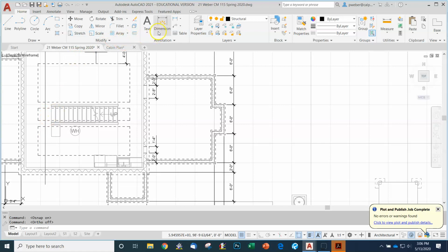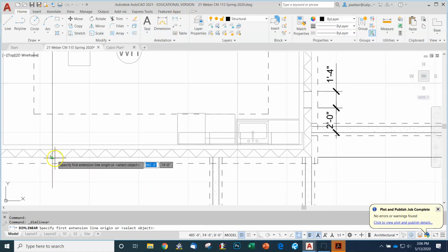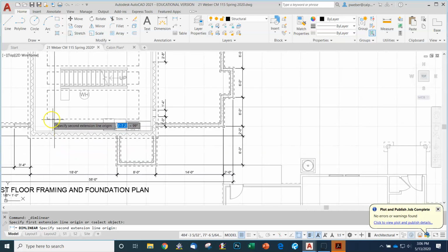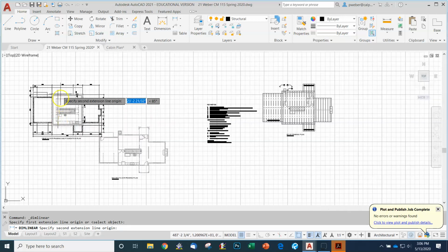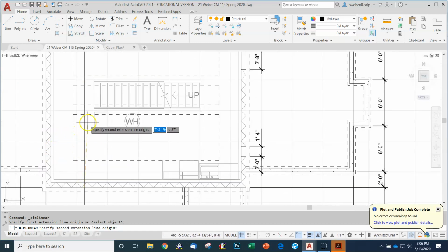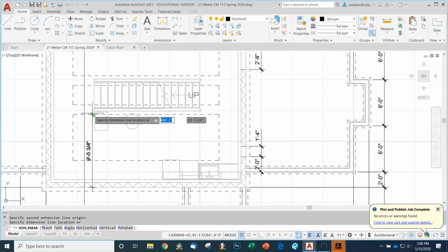And since we model it correctly in AutoCAD, we can dimension it correctly in AutoCAD. Let AutoCAD do all the work. So with O-snap turned on, I'll go to the intersection of the core face exterior concrete block. And let's see, we don't need to do this one again here or here because everybody knows it's a 4-foot footing all the way around. So I think all we have to do is just go from here to here and pull a line out.